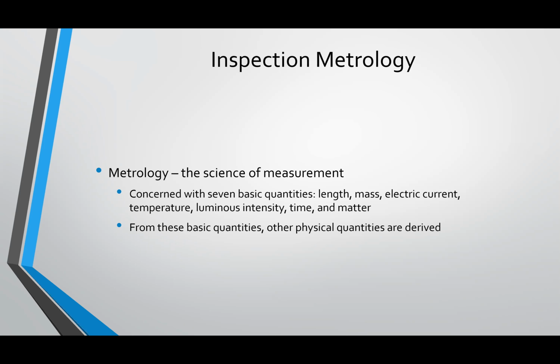But whether it is automated or manual, when we're looking at measurement, usually you're measuring a quantity with a device that is looking at length, mass, current, temperature, luminosity, time, or other quantities. In manufacturing operations, a lot of times your go, no-go gauges or snap gauges allow you to inspect a certain dimension, like a length, a width, a height, and it's a set height and it either passes or it doesn't.